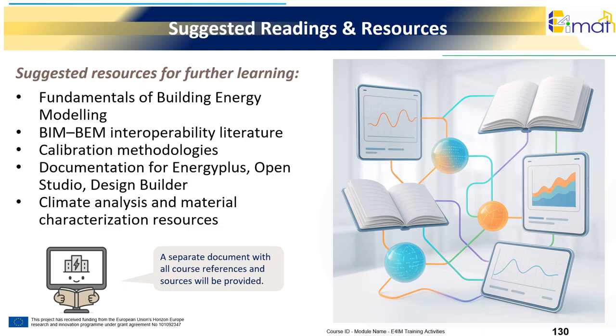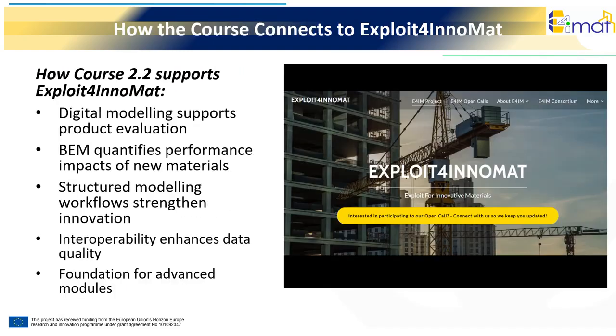Documentation for major software tools such as EnergyPlus, OpenStudio, and Design Builder can guide you through practical modeling workflows, input structures, and common use cases. Climate-related and material characterization resources can also help refine model inputs and improve simulation quality. A full document containing all references and sources mentioned or used throughout this course will be provided separately for your convenience. Building energy modeling enables quantitative evaluation of material performance under realistic conditions.